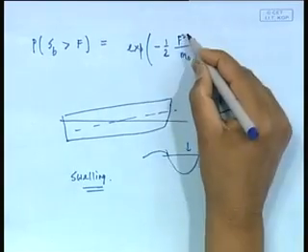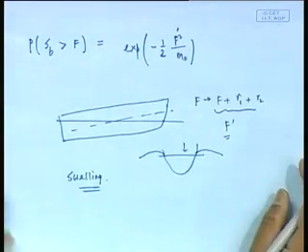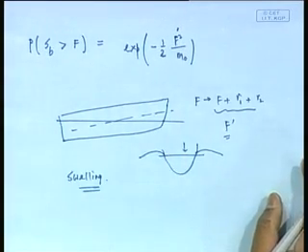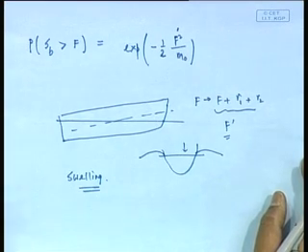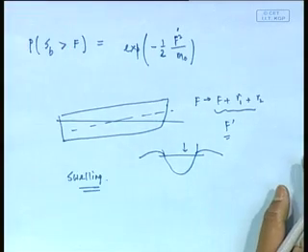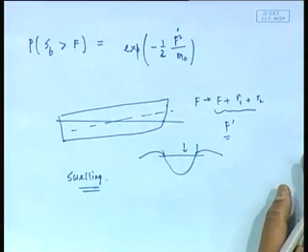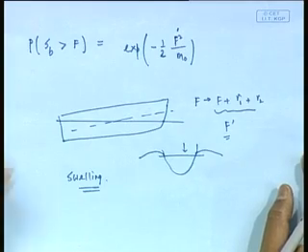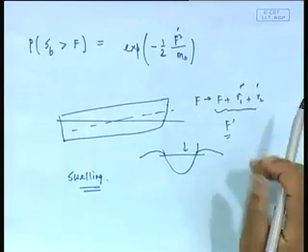So what I do is that I put here f dash. What I am trying to say, take a ship, it has got a freeboard of say 5 meter. But effectively during motion, because of this squat and because of the swell up effect, it will be 4 meter perhaps. So therefore we are going to say, if my relative displacement exceeds 4 meter, my deck will get wet. That 5 becoming 4 can be determined from empirical formulas.